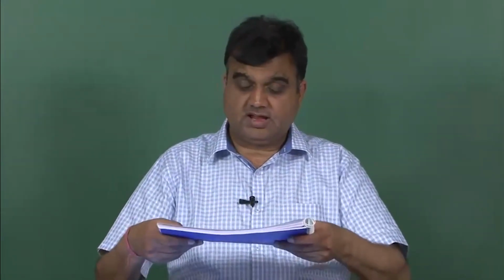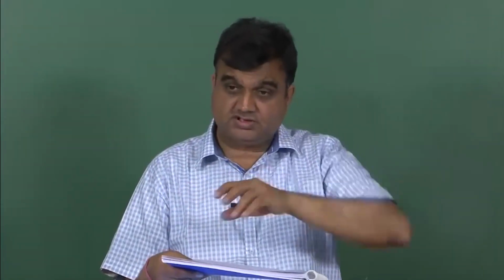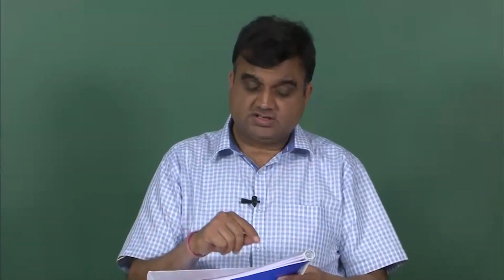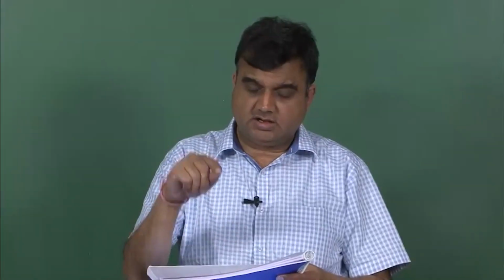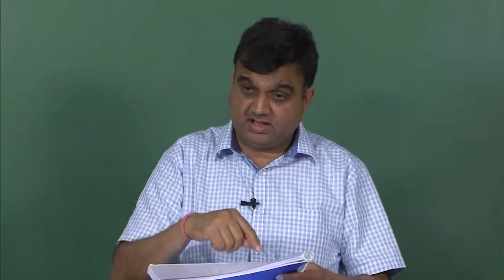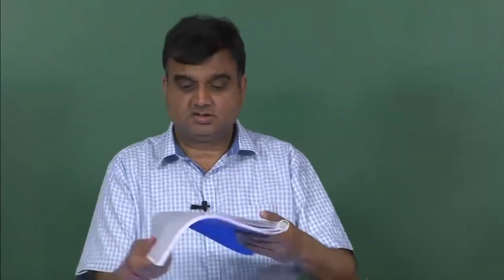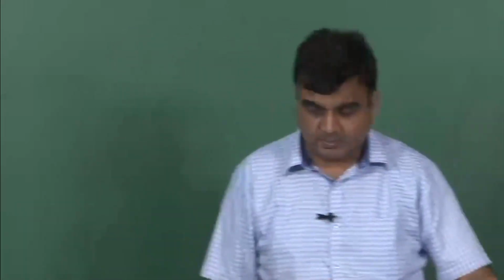So, you can have a plate which has curvature in this direction, that direction, and also a cross component. So, the slope is changing, the second derivative of W with respect to x and y is non-zero. So, that is called twisting. If I am trying to twist it like this, that is the twisting thing.